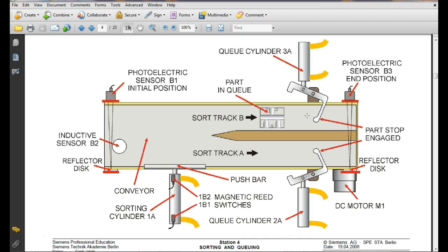It surprised me that Amatrol didn't put a sensor on this because of the number of sensors they put on there that they don't even use. That's not even in the program. They're available for us to come back and write programs around, but they're not in the original Amatrol program. Like the analog pressure switch. It's got an analog pressure switch on it. It's got an encoder on it. It's got an inductive sensor on the sorting station, so it could sort metal and plastic. But when they wrote the program, they just incremented every time.